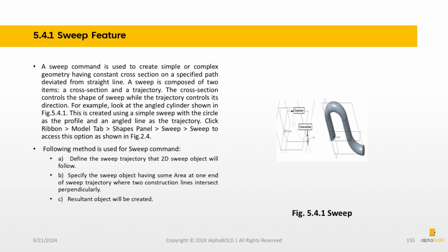For example, lofted profile between circle and square, square and triangle, etc. In this case, divide command is used for this purpose. In the example, two sections are used. Section 02 is square with four corners as vertices, while circle has no vertices at its boundary. Click Ribbon, Sketch tab, Editing panel, Divide to access this command.